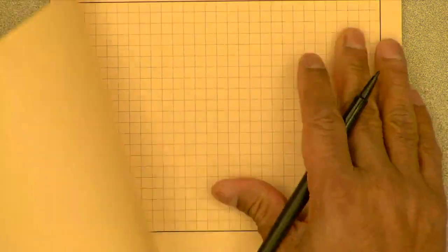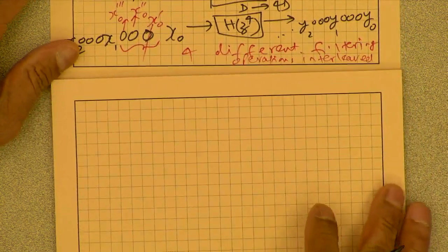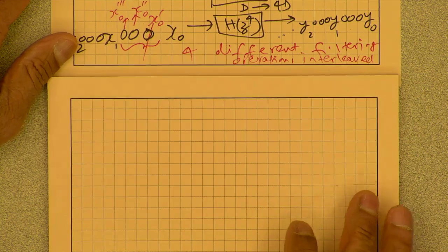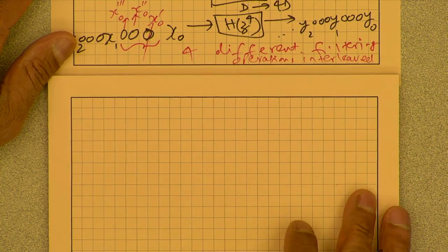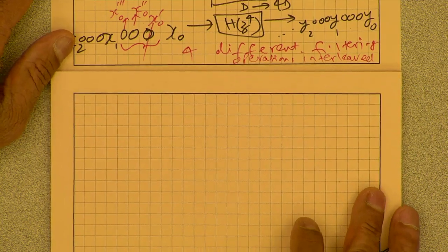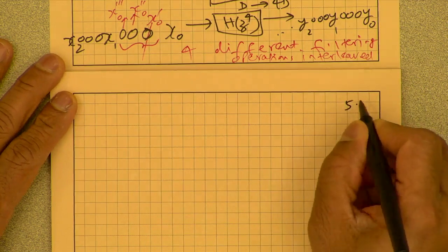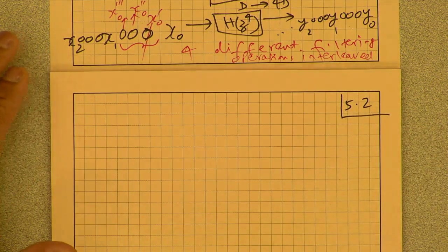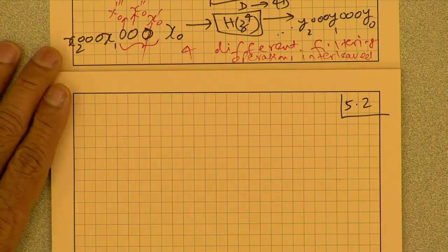Okay, so we have completed the concepts of pipelining, and we have talked about interleaving, and those are all in the context of feed forward circuits, circuits with no feedback. We saw that any time we have a feed forward circuit, we can pipeline it by adding delays at appropriate feed forward cut sets.